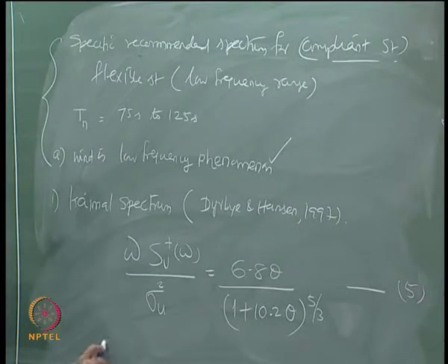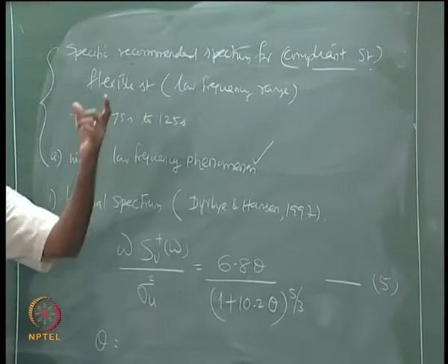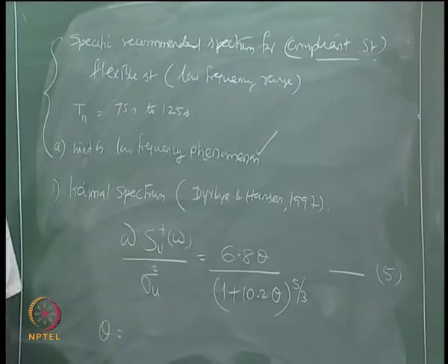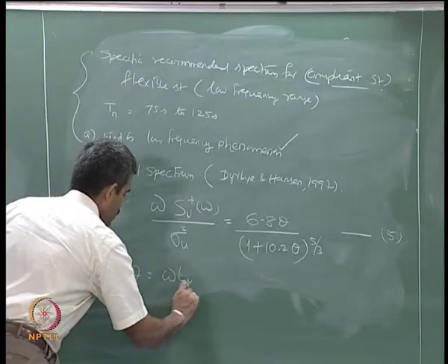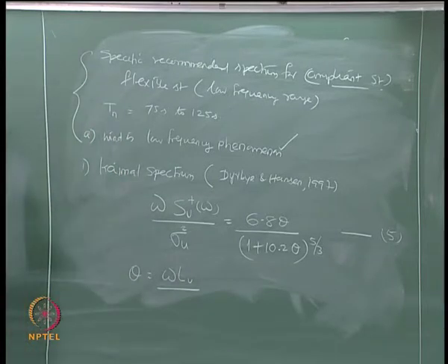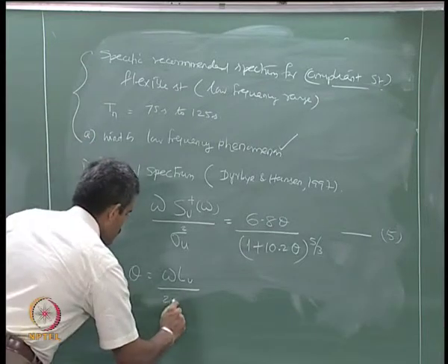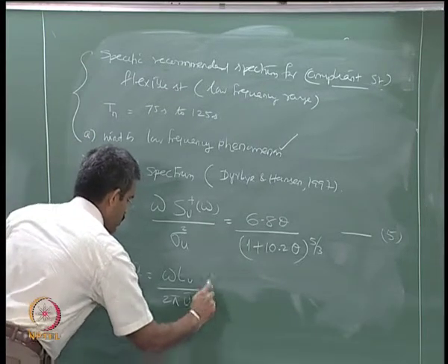So, theta in my case is the same dimensionless value as specified in the Davenport and Harris spectrum, which is omega Lu by two pi u bar.